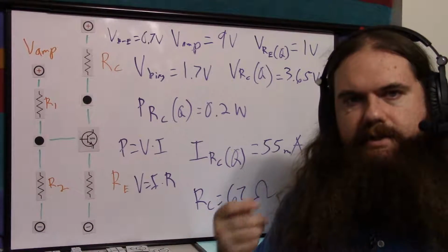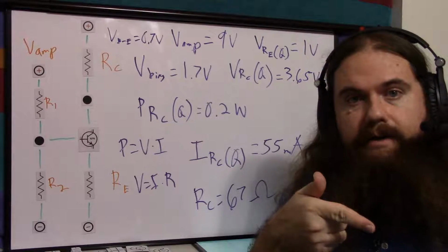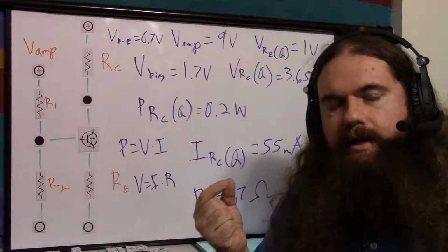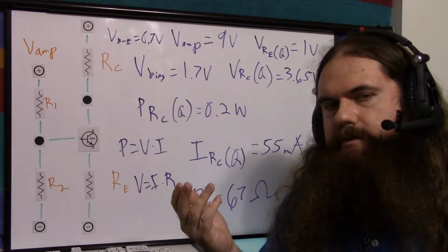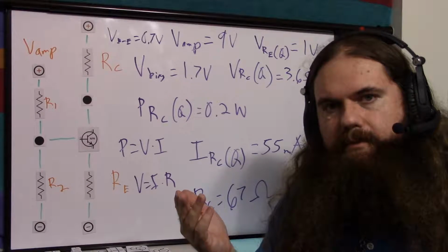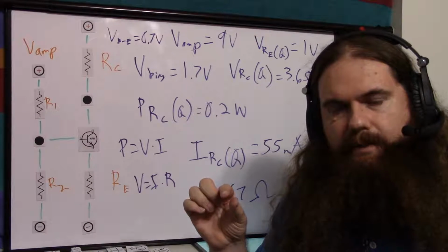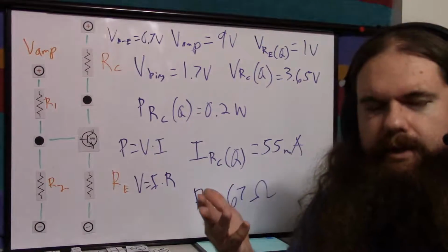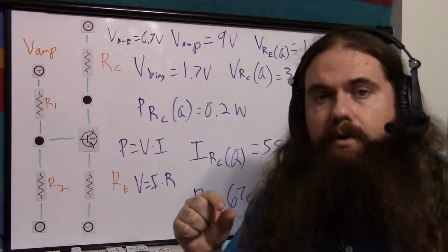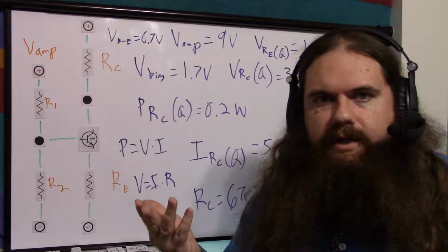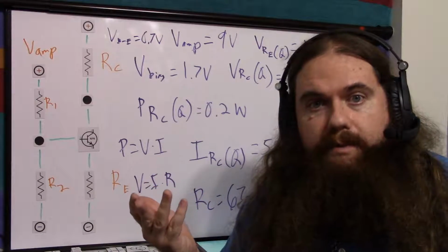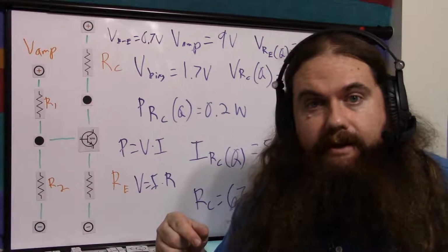But you're going to need good resistors, you're going to need good transistors. When I try this, it actually ends up heating up the transistor quite a bit. Now, they're rated for 650 milliwatts of power dissipation, and when I'm dissipating only 200 some milliwatts, they get warm. So I'm just trusting the spec. Perhaps them being that warm is perfectly fine, but be aware that they are getting warm.